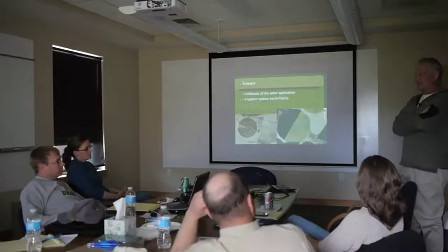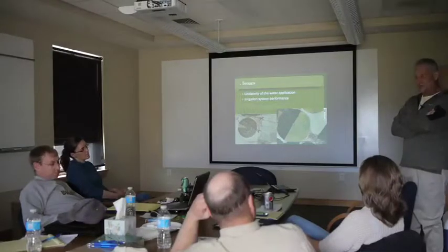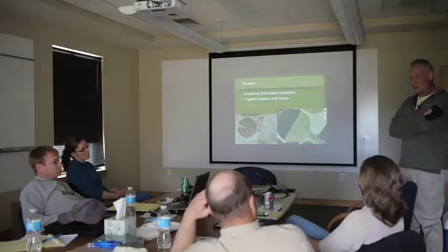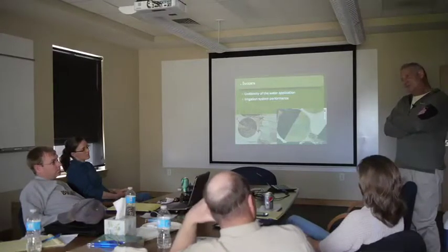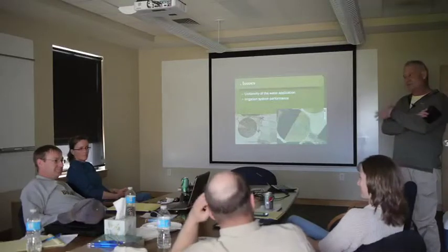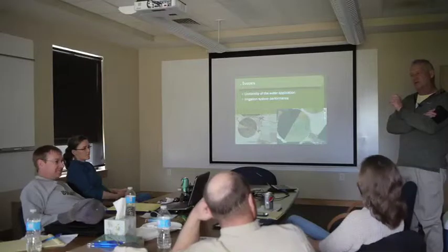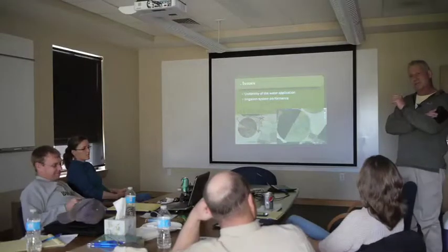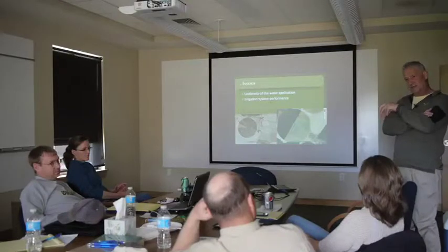There's a couple of things that the end guns do that I think are a burden on the efficiency. One is that they don't apply the water very well to the ground. I mean, yeah, they get water there, but there is a lot of wind drift from them, and also those have a higher pressure requirement than the drop sprinklers.